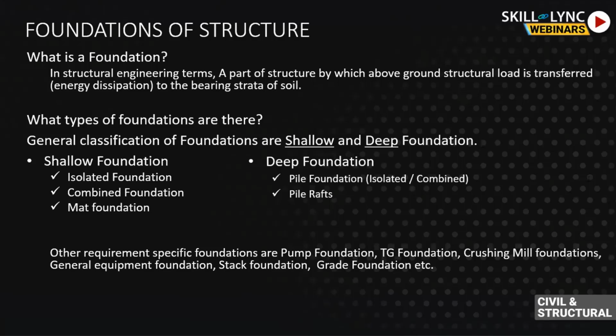Okay, a geotechnical report can suggest different types of foundations. It could be a shallow foundation, or isolated or mat foundation. It could be a deep foundation, which could result in piles, or it could have soil improving techniques, which would require micro piles. One needs to understand all these suggestions before selecting a soil strata for founding their structural foundations, and come up to a certain depth. And then the geotechnical report would suggest a bearing capacity as well.